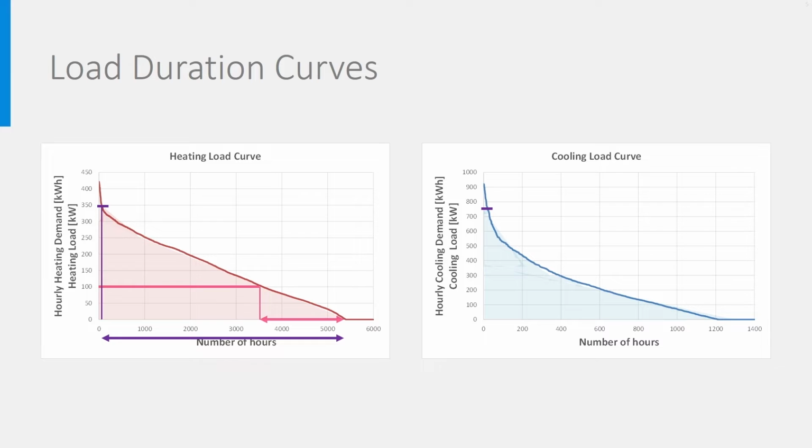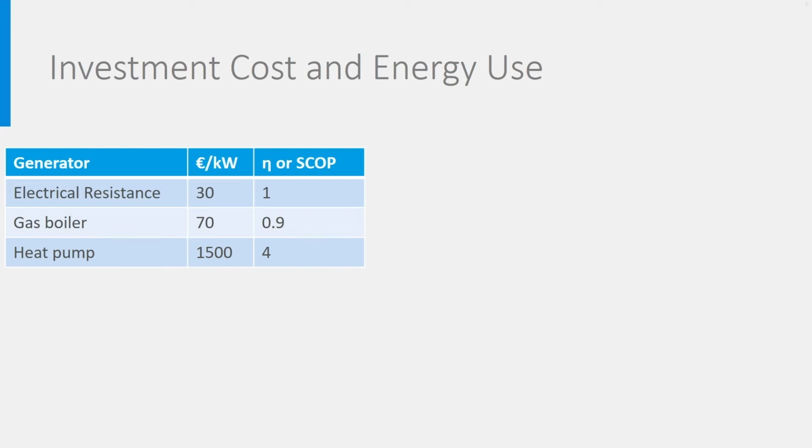The message here is that the relationship between the load and the corresponding energy demand is not linear. In both heating and cooling cases, with a load of 83% of the nominal one, we were able to cover more than 95% of the total energy demand. And this is a very interesting feature when sizing HVAC equipment in relation to its price.